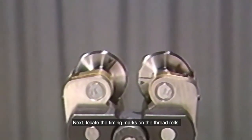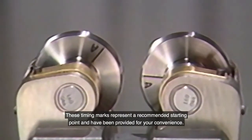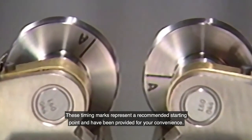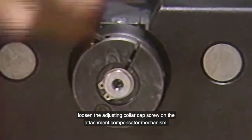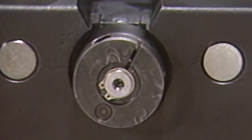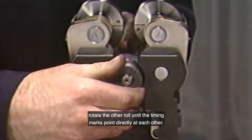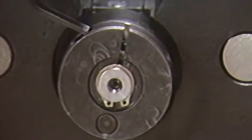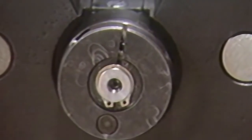Next, locate the timing marks on the thread rolls. These timing marks represent a recommended starting point and have been provided for your convenience. If you choose to use the provided timing marks, loosen the adjusting collar cap screw on the attachment compensator mechanism. While holding one roll, rotate the other roll until the timing marks point directly at each other. Securely tighten the adjusting collar cap screw. Rotate the compensator to make sure the timing marks come back to each other.